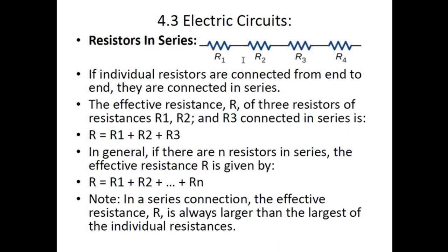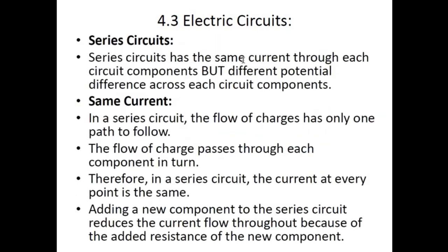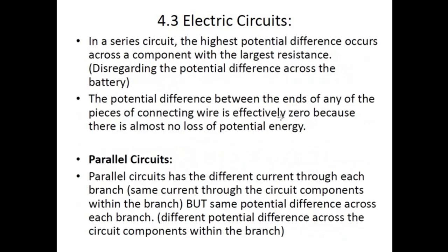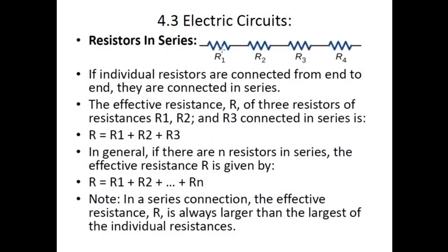Next we have resistors. Although we draw resistors like this, resistors can also be drawn using this symbol. If you connect some resistors in series, their total resistance adds up. Like between this point and this point, all these 4 resistors would have a combined resistance. For example, this was 10 ohm, this was also 10 ohm, this was 20 ohm, and this was 10 ohm. So between this point and this point, the total resistance would become 50 ohms.